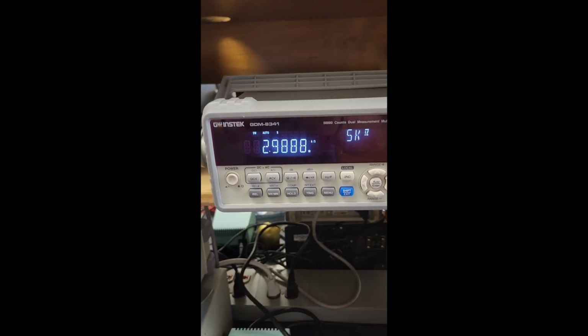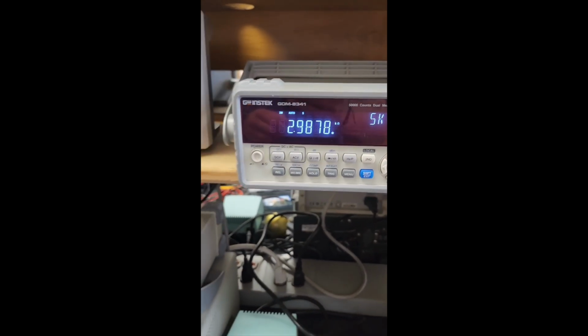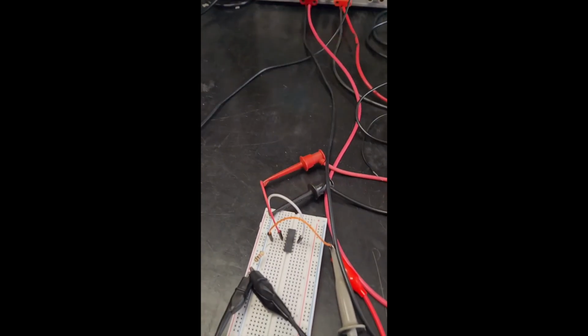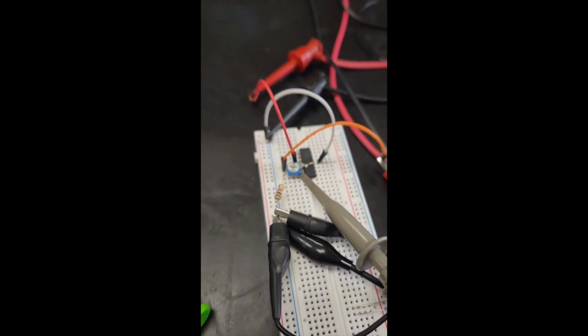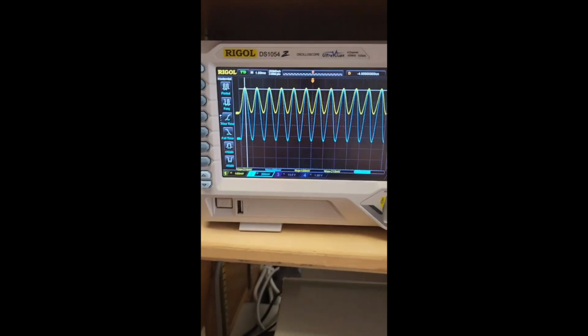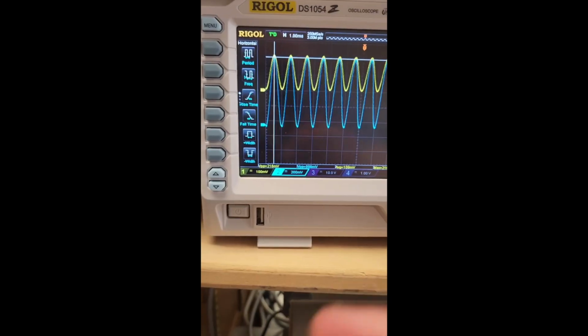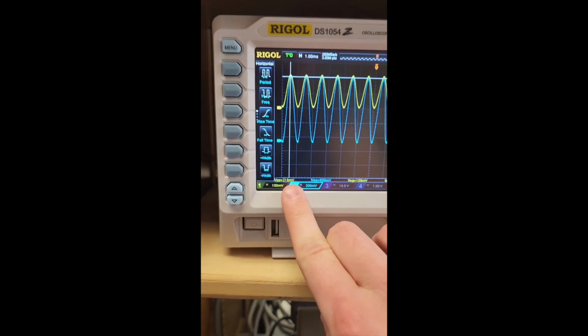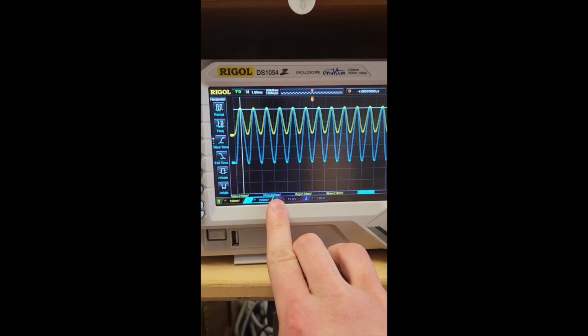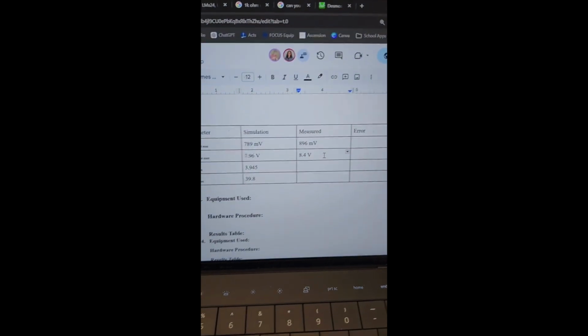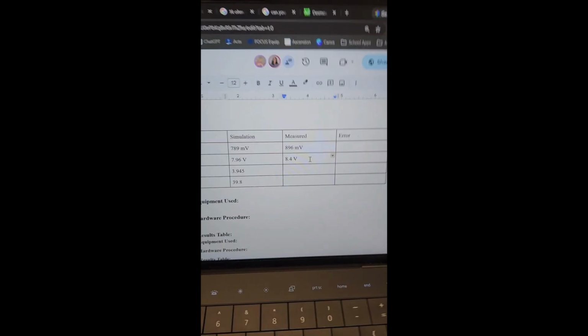Our error most likely being due to our potentiometer not being exact. After now adjusting our potentiometer to be approximately 3K, we can now get the minimum gain of our circuit. After inserting our potentiometer back into the circuit, we can find that our gain is approximately 4, with our input again still being around 200 millivolts, and our peak to peak of the output being around 896 millivolts, which is again a little higher as well.